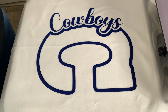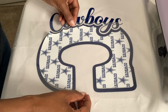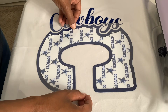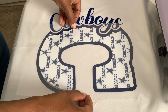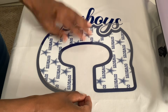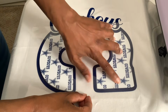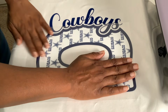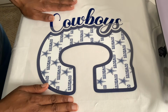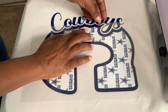Now I am going to layer in my printable heat transfer vinyl, and when I layer it in, I want to make sure that I get it layered in without overlapping any of the Stripflock that is already on the shirt. And I'm just going to line that up as best as I can. And once I'm satisfied, then I am going to press this at 320 for 20 seconds.